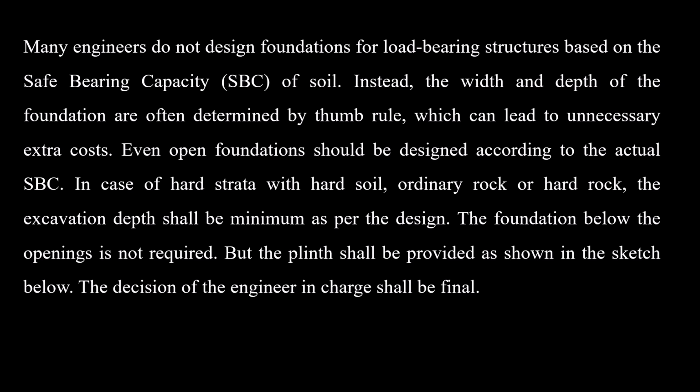In case of hard strata with hard soil, ordinary rock or hard rock, the foundation excavation depth shall be minimum as per the design. The foundation below the openings is not required, but the plinth shall be provided as shown in the sketch below. The decision of the engineer in charge shall be final.